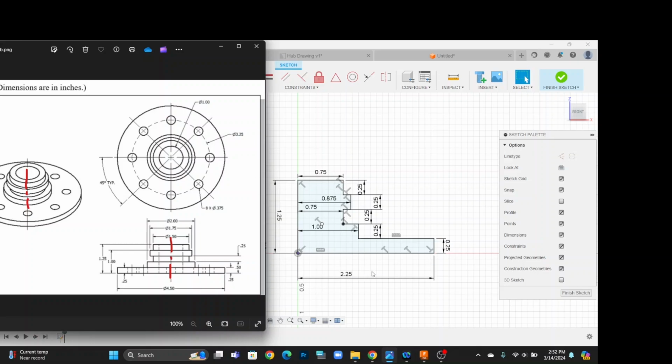So in the sketch, which is only the right half of the object, I have used 2.25 inches, which is half of 4.5. However, the vertical measurements which are along the z-axis are exactly the same as is here. So I have an overall dimension of 1.25 inches, which matches what is in the sketch.